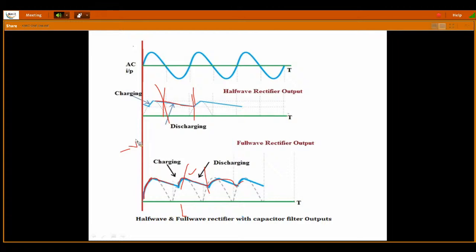through the diode D2, which also contains the AC ripples and DC component. Whenever those AC ripples are more than the stored capacitor value, they can charge the capacitor. Initially, due to the diode D1, the capacitor takes the charge. Whenever it is the negative cycle, due to the diode D2, the capacitor is going to take the charge. Now this is a common point, and here you are applying the capacitor. This is the load resistance. Initially diode D1 is conducting, so the output will contain the AC ripple content as well as the DC content. Due to this AC ripple content, the capacitor is charging.